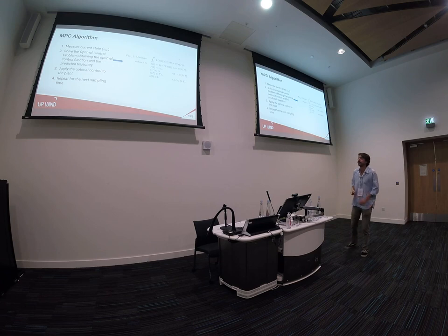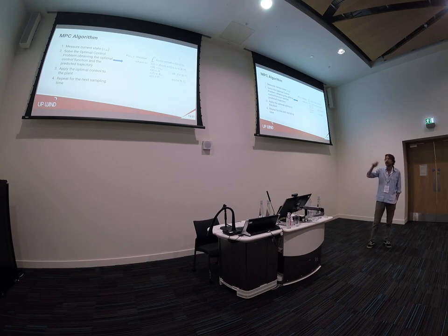And then we solve this optimal control. And well, basically from this optimal control, we get a resultant trajectory, a predictive optimal trajectory. Okay? And from this optimal control, we also get a predictive optimal control input over time. And we take this optimal control input and we feed it into the system. Okay? And then in the next time step, we measure the state again, and we keep on solving optimal control problems in every time step. Okay? That's basically the idea.